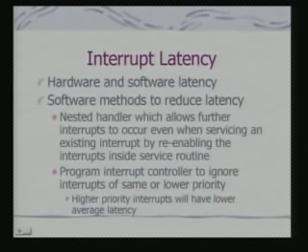Even in software, we can take certain steps. There are software methods to reduce latency. One of the steps is what is called nested interrupts. A nested interrupt handler allows further interrupts to occur even when servicing an existing interrupt, by re-enabling the interrupts inside the service routine.